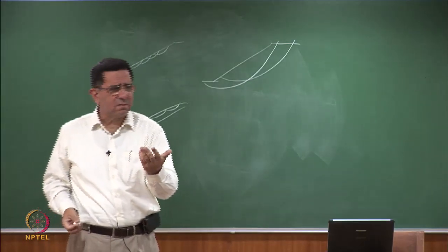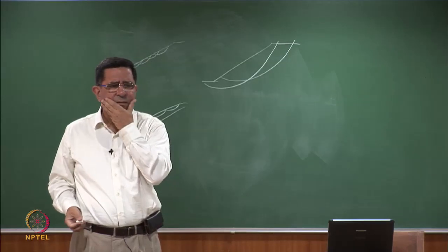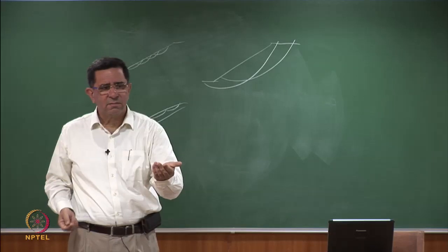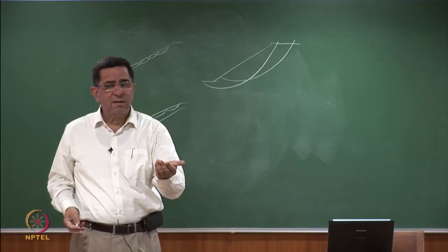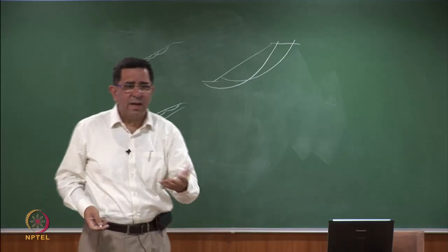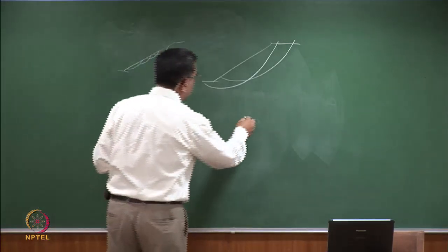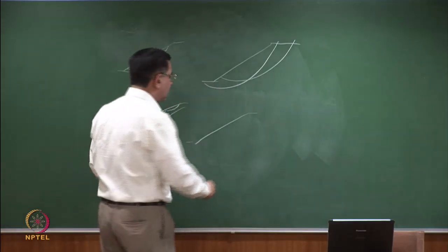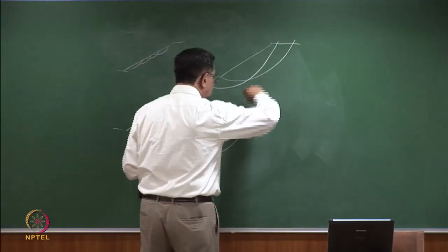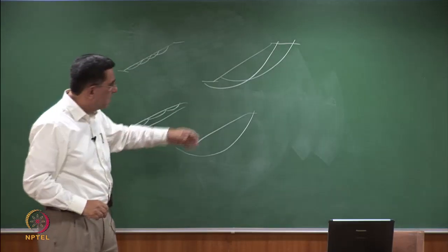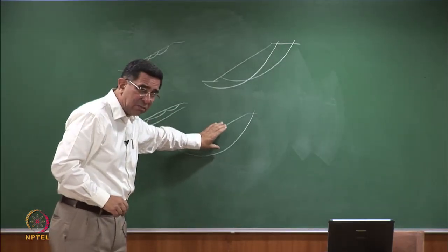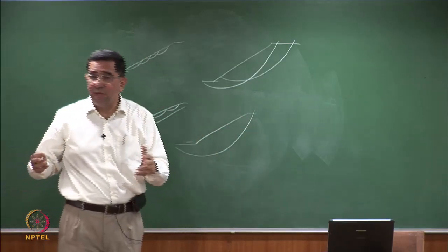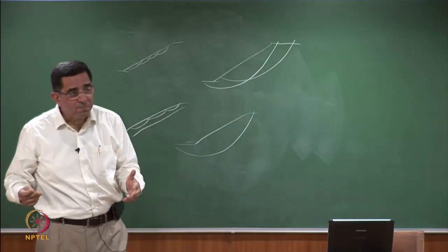Whereas another soil slope, the Tehri Dam, how high is it? 220 meters. I think it's more than 220 meters. Anyways, let's take an earth dam, earth cum rock fill dam more than 200 meters high. But here, the failure surface can go through the foundation also, depending on whether it's on a soft foundation. So when the thickness or the depth of the failure surface is comparable to the height of the slope, then you have a finite slope.